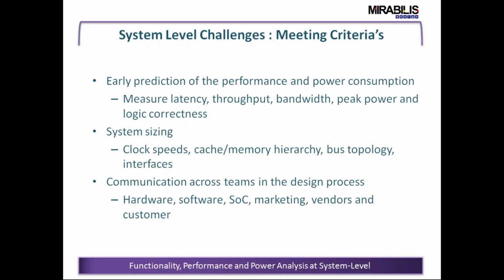So system level modeling helps you to predict the performance and power consumption of your complete system platform by measuring the latency and throughput, or bandwidth, and peak or average power consumption of the platform, and how exactly the applications are executing on the target platform itself.